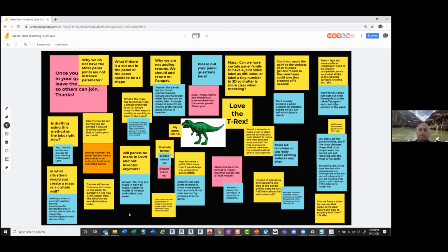I was just wondering about the type, because they are adding a different type of panel while in the takeoff, so it will generate a different type, right, if it is a different dimension? Is that correct, Zach? I'm not sure I understand. There are 5 parameters that they can put into Revit on each of the panels that tell it stuff like elevation, panel type, subtype, and fab number. And then the takeoff program also reads the geometry of the unpainted panel faces. So the panels get categorized by all those different pieces of data, by their geometric shape and the other 5 parameters.